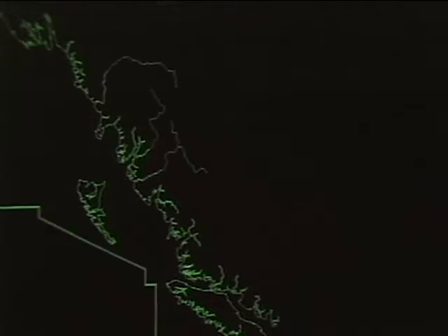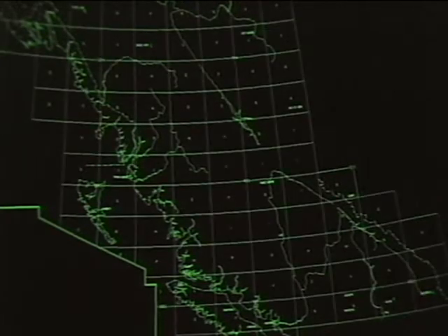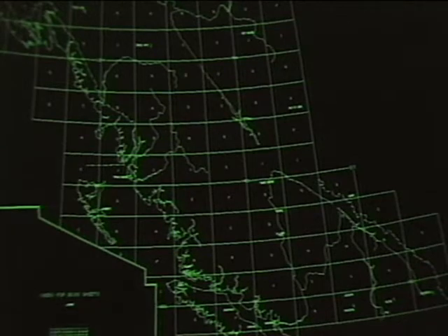The Ministry now receives digital base map information from the Ministry of Environment. Each map sheet is bounded on the north and south by lines of latitude 6 minutes apart, and on the east and west by lines of longitude 12 minutes apart. For easy indexing, these sheets are clearly defined within the National Topographic System and can be further subdivided for larger scale mapping.